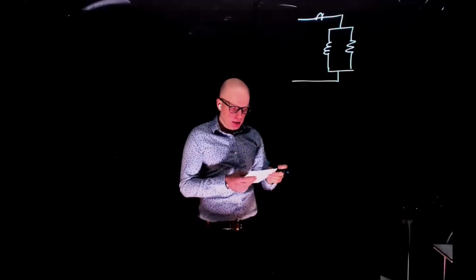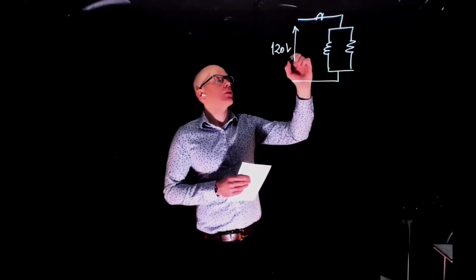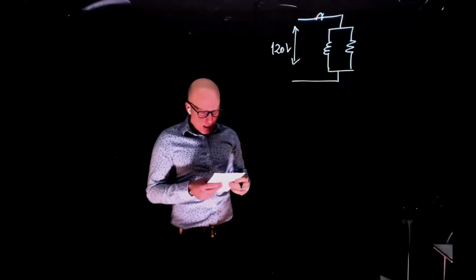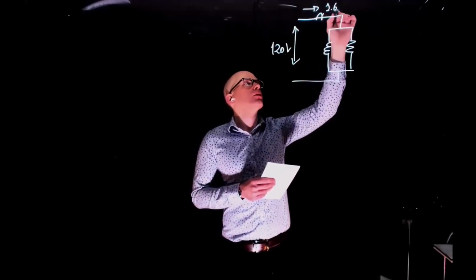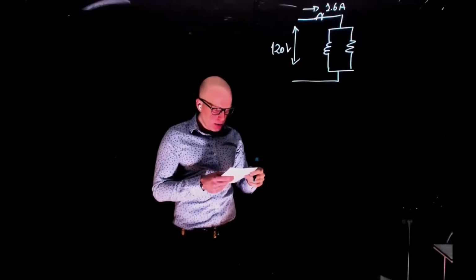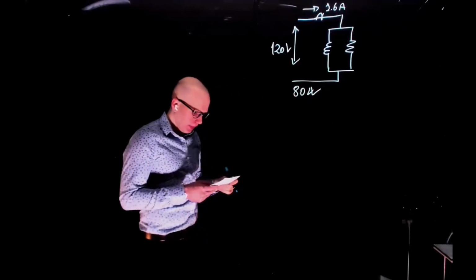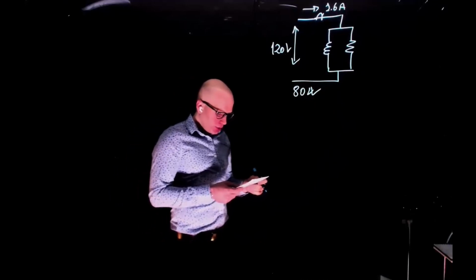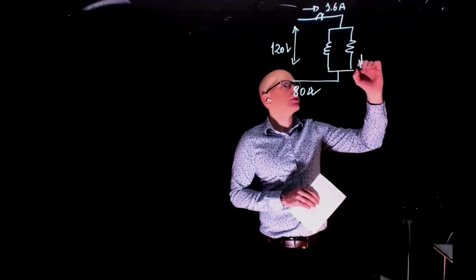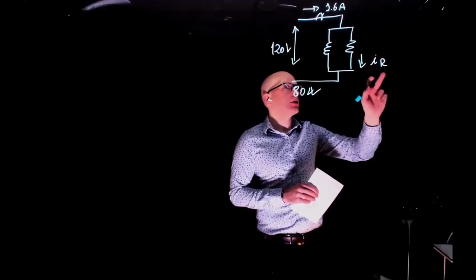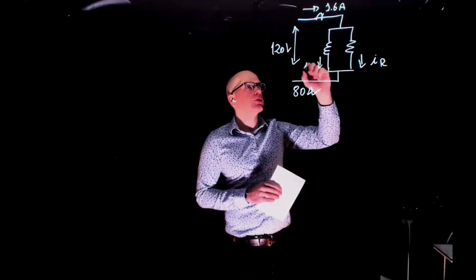So we are applying here 120 volts, and this is taking 1.6 amps and is dissipating 80 watts. The first question is, what is the current IR that is dissipating energy in the core, and the other question is what is I phi?